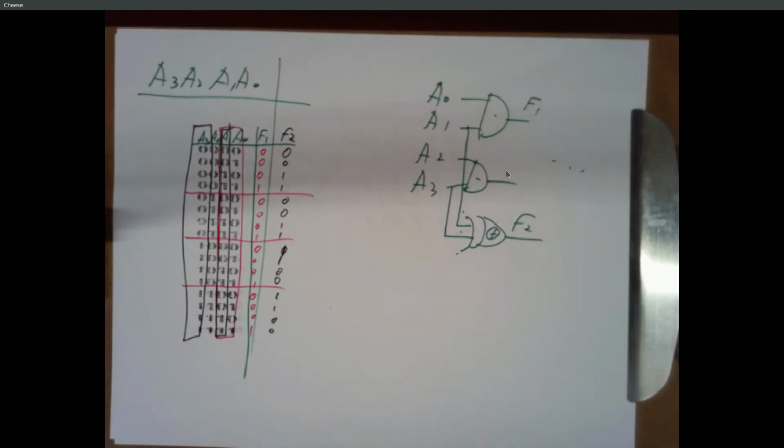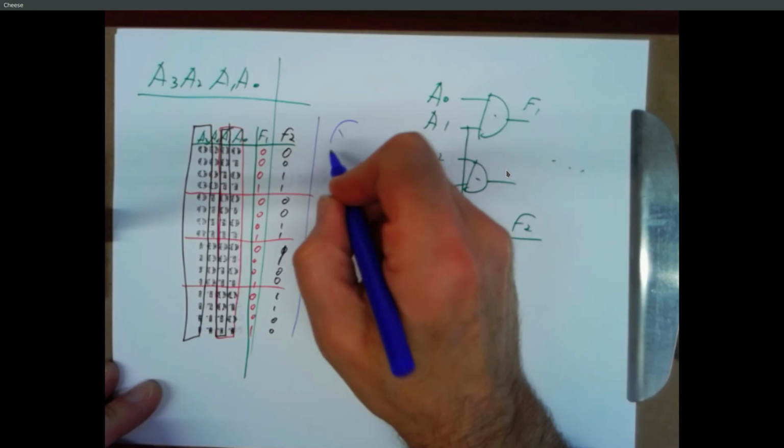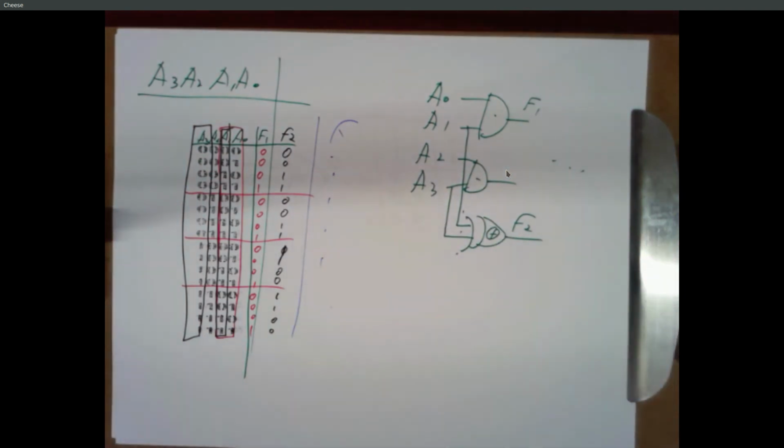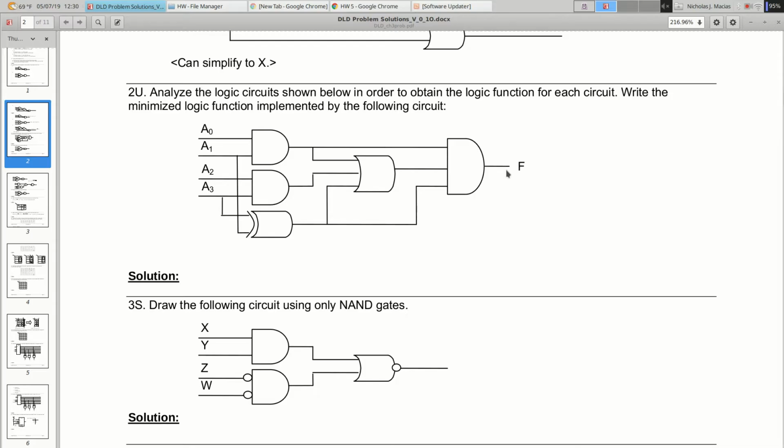So once you have your final value for F, right, go ahead and make a K-map, fill in the ones, cover them, write down the minimized equation, there's your final answer. And I think it would be cool to do that and also try to take the original expression for F and simplify it, see if you can make them the same. Because someday that'll be useful.